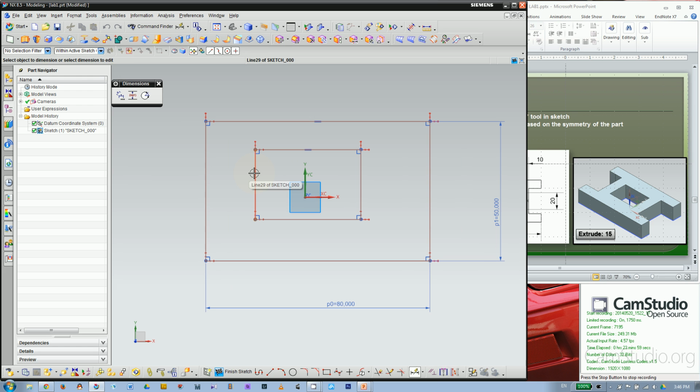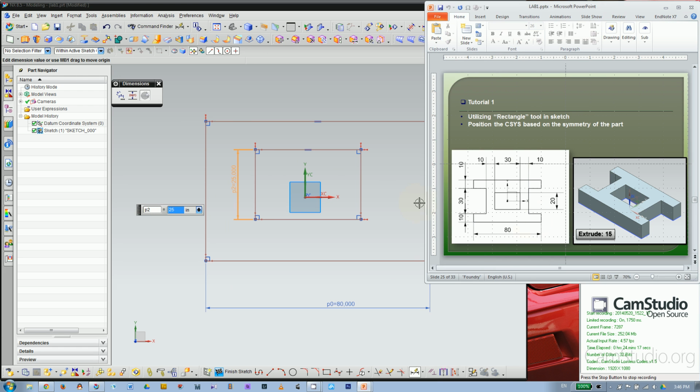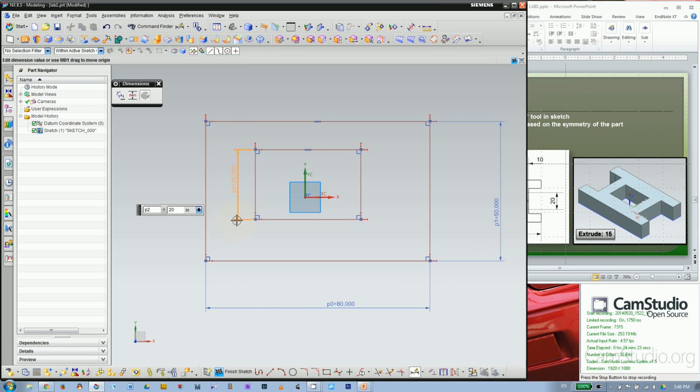If you click a line, that will be the length of the line. See that? And you can click the second time to put down the dimension. Now in here, you can type in a number. And as you can see in this slide, the smaller rectangle is 20 inches in height. So 20. And you can just click something else or continue. But I also recommend that after you type in the length, you hit enter. Now you can have a review of how big your dimension is.